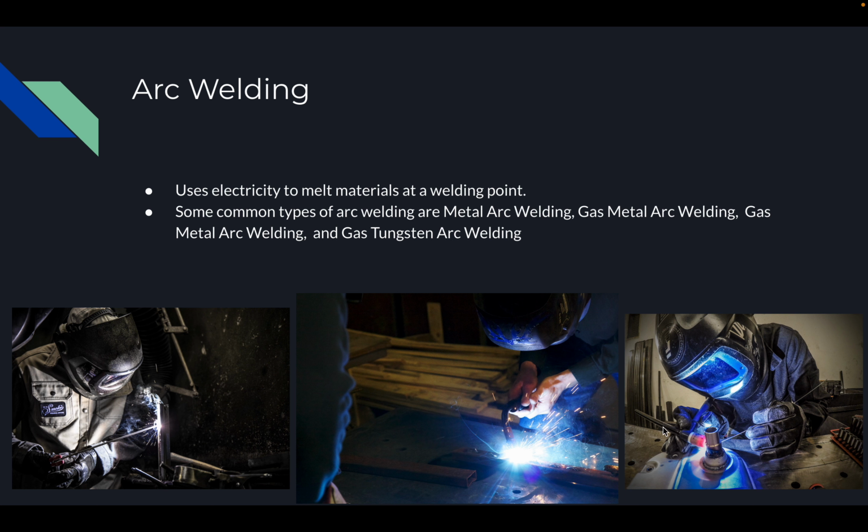And then over here, the stinger is sort of the same as the MIG welding, but he has a different tip right here, which is called a cup. And then in the middle, he has a stinger. Basically, what he does is he puts a cup on the side at an angle, as you can see right there, and he'll lean it back and forth, and he'll sort of just follow up with the metal rod, and that's how he creates his bead or his weld.